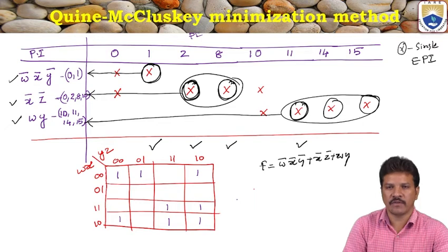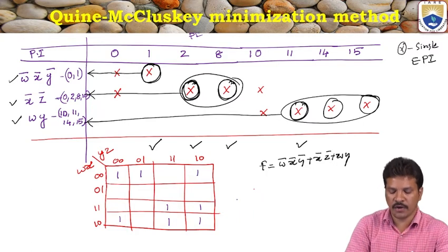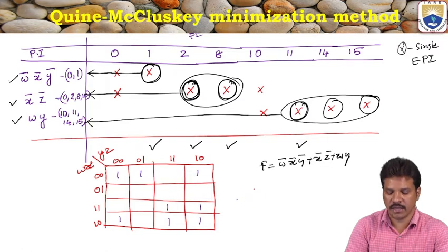According to the Karnaugh map, first check for all ones, 16 ones in the square boxes. If it is not there, then go to 8 ones. Is there any 8 ones in the square boxes, like a rectangle, 8 ones in a rectangular shape? So no, there are no 8 ones. Next step is 4 ones. Is there any 4 ones?